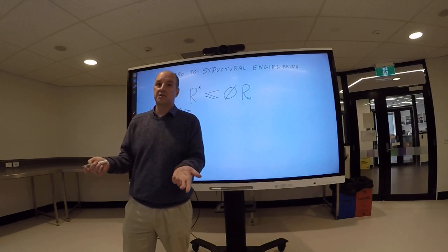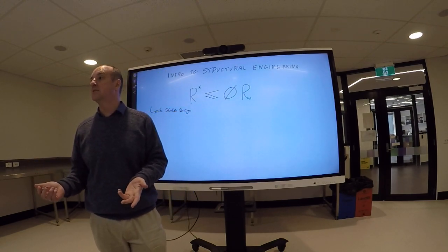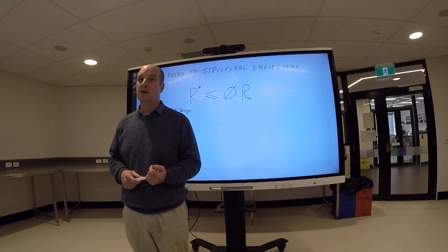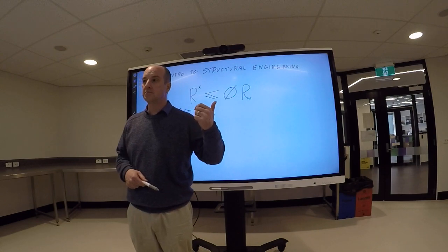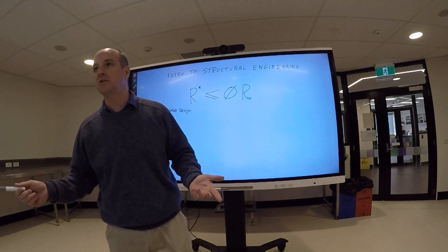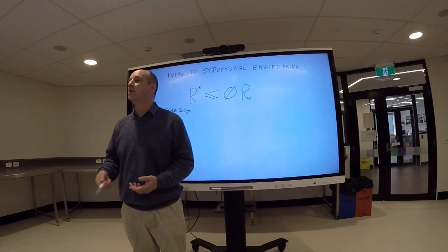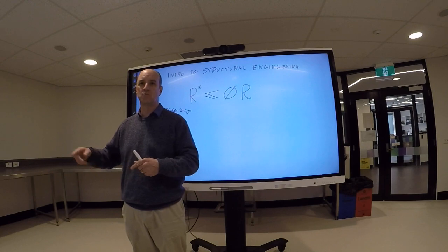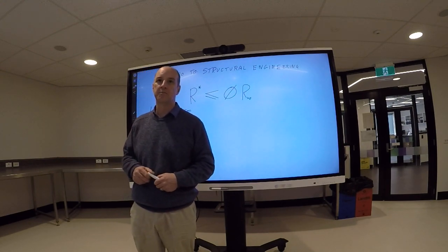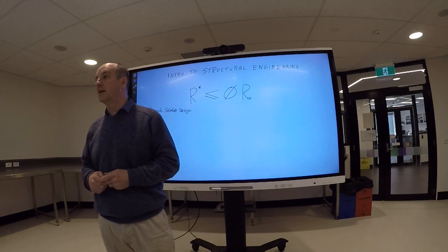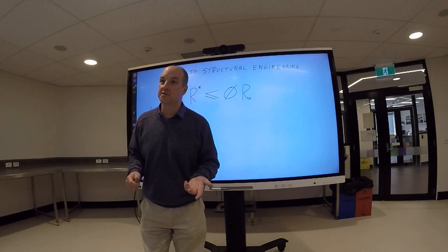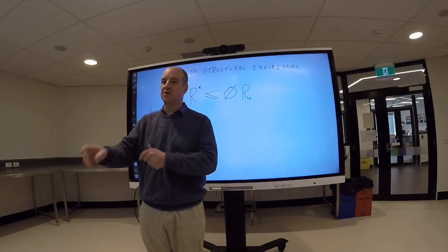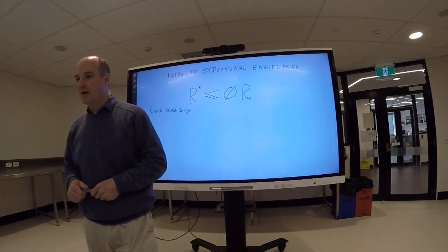When you come to design a structure then, if you want to design a steel structure, you have to look up the steel code, which is AS 4100. If you want to design a timber structure, you're going to be in 1720. You'll get to know these numbers, or you can Google Australian code, AS wind codes, or timber code, that kind of thing. There's a lot of them that you'll get very familiar with. 3600 is a favorite for engineers because that's the concrete structures code. Okay, and a lot of these codes then refer to each other.